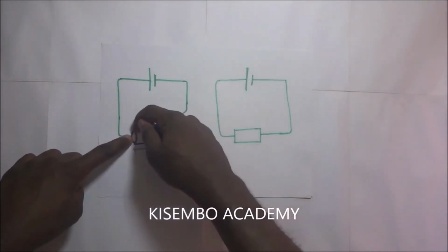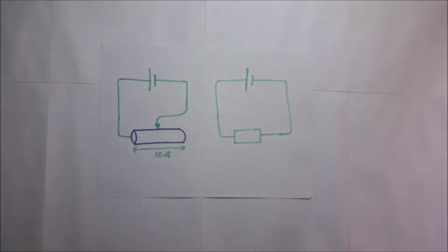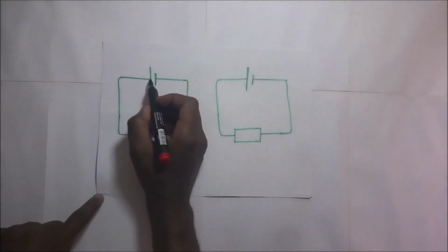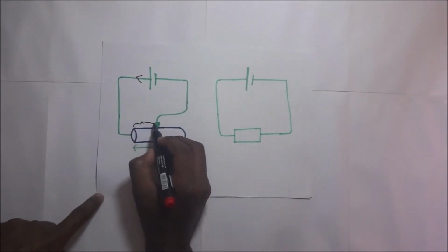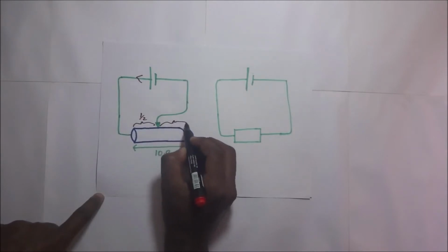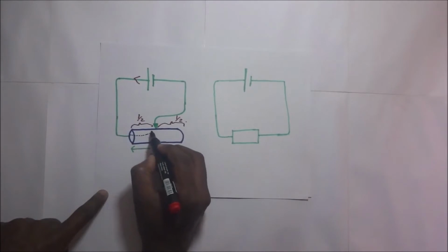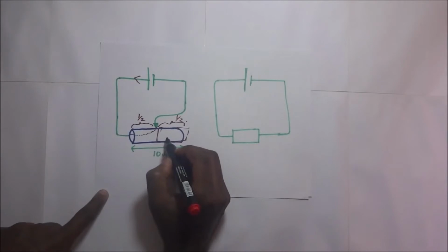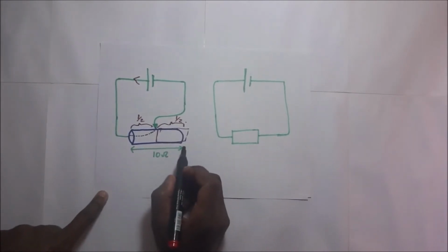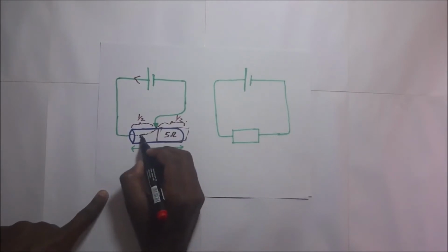And when we slide this wire across here, it means we are regulating the resistance of this. If this is our cell, for example, we know that current is flowing in that direction, and if that slide wire is, let's say, halfway, it means that current will come and only flow like that, leaving this other part redundant. So if this thing is 10 ohms and the slide wire is halfway, this is 5 ohms and that is 5 ohms.